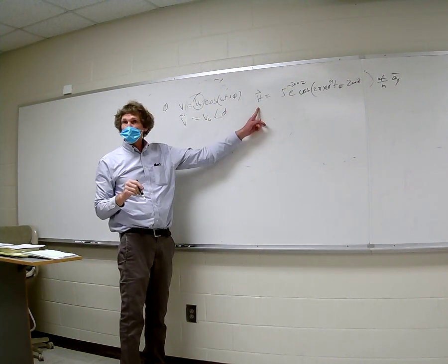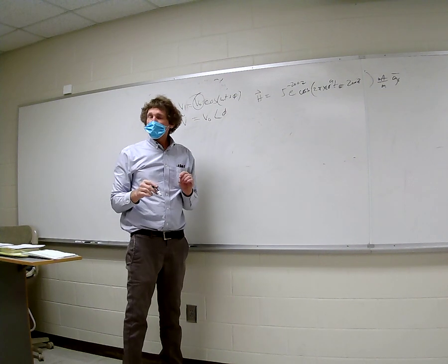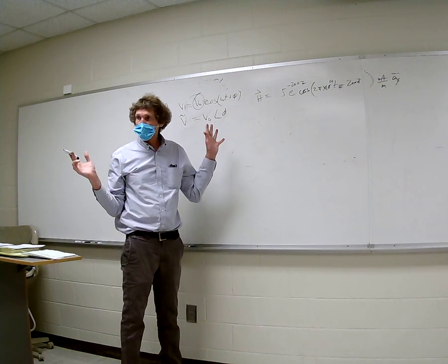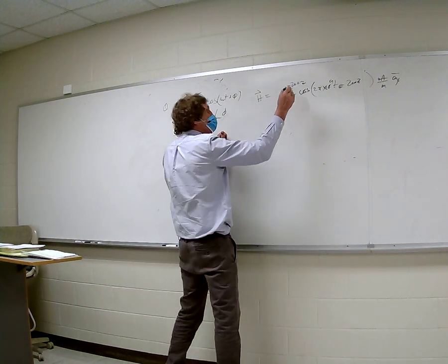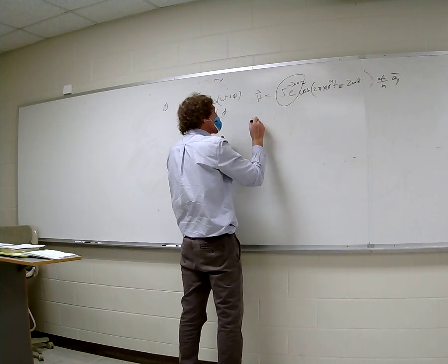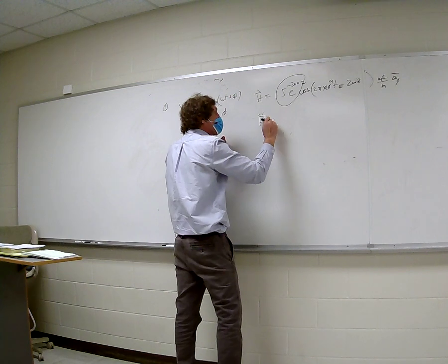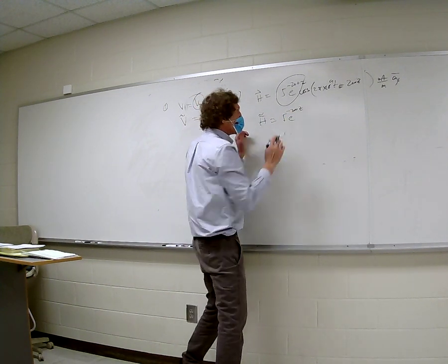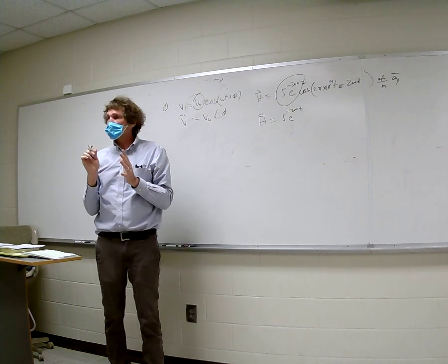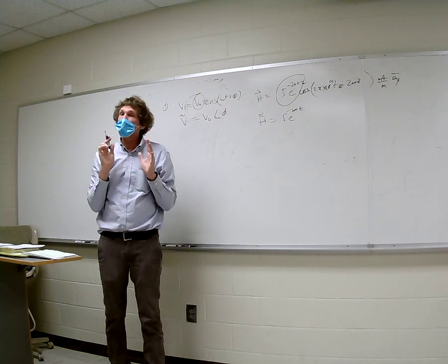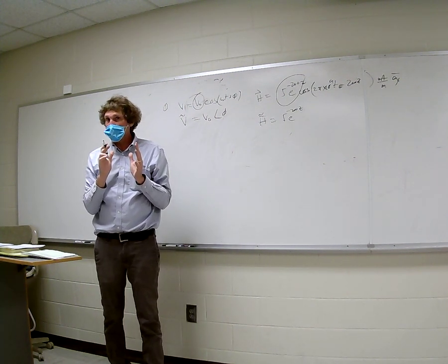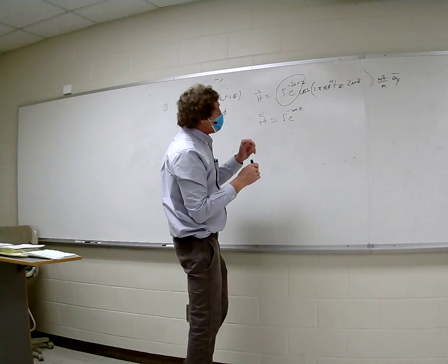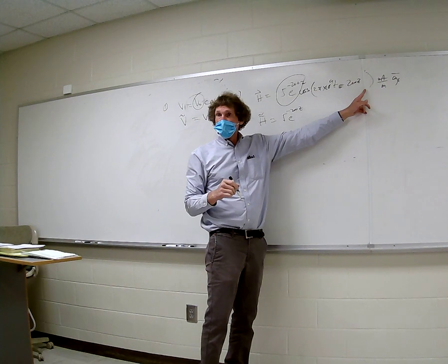When we go to the phasor domain, do you remember this problem, by the way? Some of you. All right. Here is the magnitude. So H phasor would be 5e^(-200z). And remember, e to the minus 200z is a real number. Admittedly, it's decaying in magnitude, but it's a real number. Now, there is no phase angle like this.